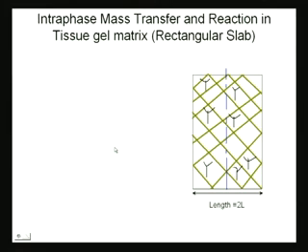we have been able to convert a heterogeneous model, which is quite difficult to solve, to a homogeneous model. We call it a pseudo homogeneous model because it is not really homogeneous, we are just assuming it to be homogeneous. So, once we have been able to write the pseudo homogeneous model, then we can write a reaction rate just like a homogeneous reaction rate, which is first order, Kv times C. And again, why are we doing first order?